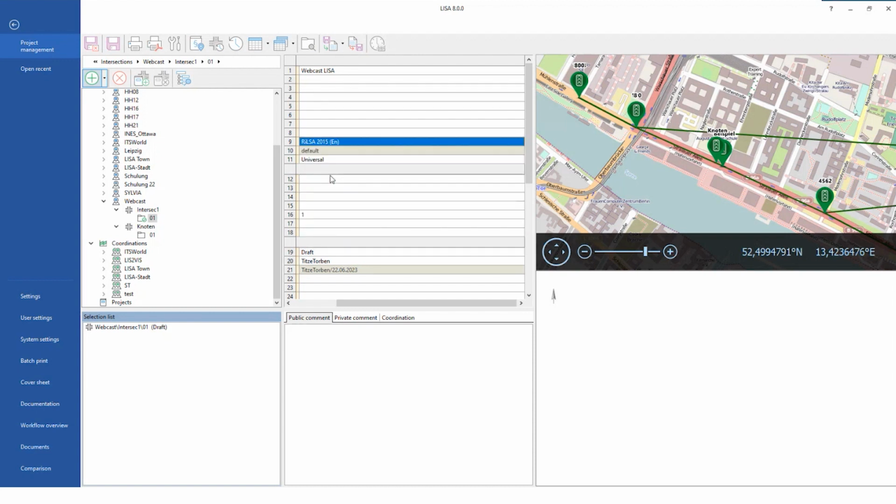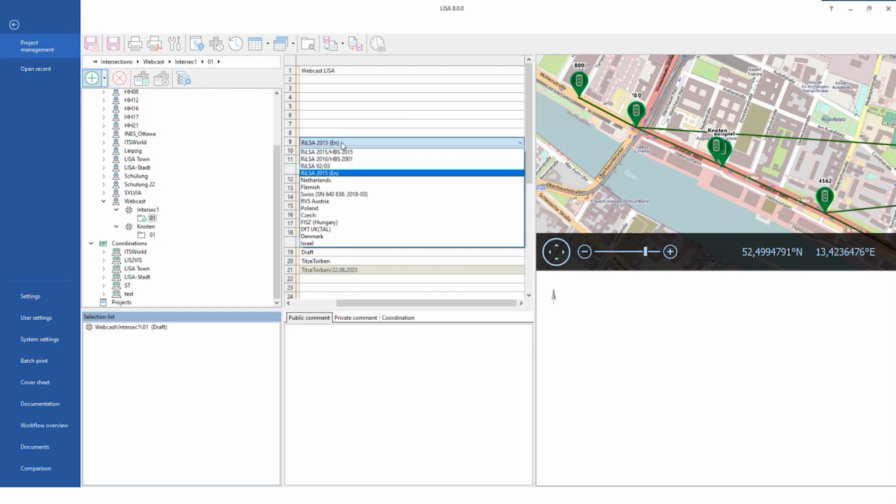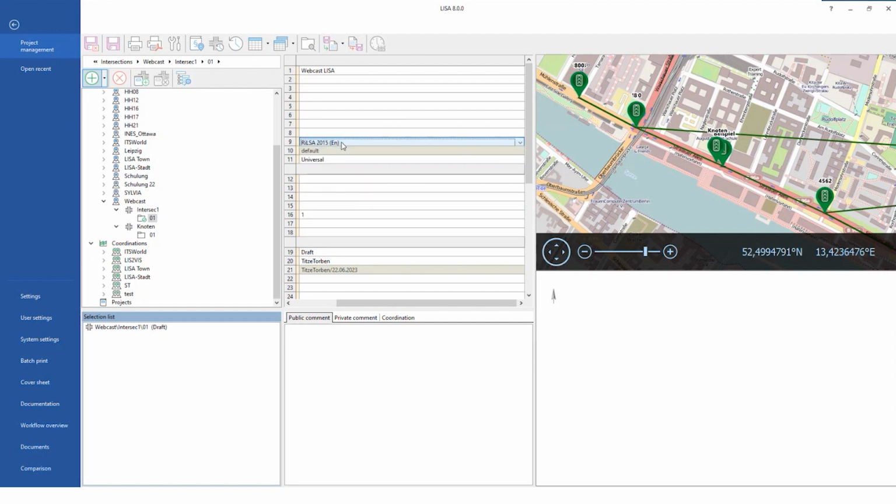When you go into the detail, you're always finding that it comes down to where is actually the collision point? How do you deal with the entering vehicle, with the leaving vehicle? What are the different speeds? But we'll come to that. If your country is not listed here and you're not happy with what the German guidelines have to offer, then we have to take a look at it and maybe find a way to make certain changes. Usually, you can get very close just by changing the settings in the intergreen time calculation module.